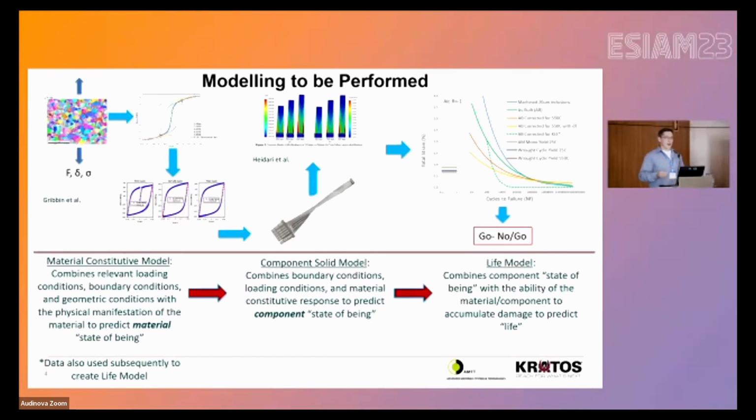And especially with a hypersonic assembly, we have lots of interfaces, lots of interactions, lots of cycling. So the boundary conditions and the loading conditions were non-trivial inside of the finite element solid model. First, can we capture the constitutive behavior? Second, can we implement that within a finite element solid model that incorporates all loading and boundary conditions? Third, can that assembly predict the current stress and strain of the component such that we can then predict life?